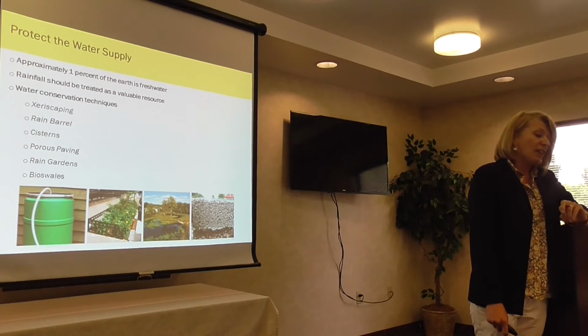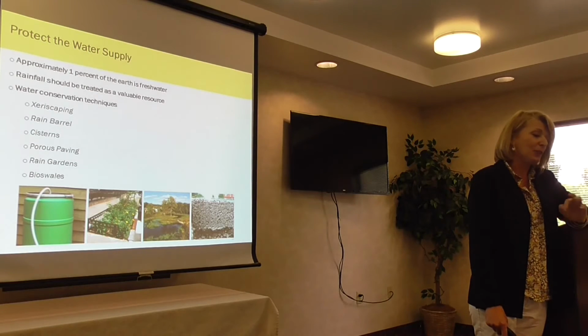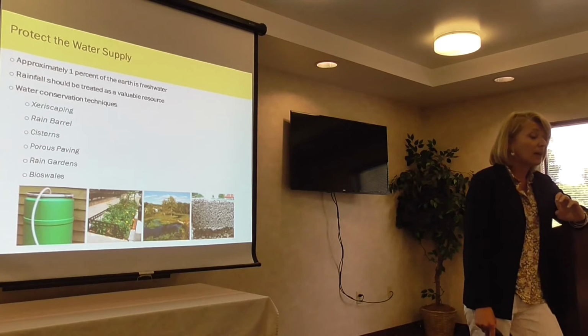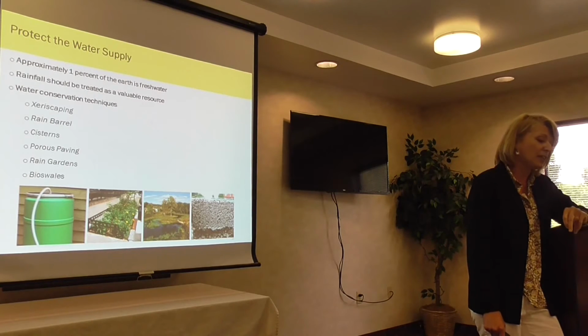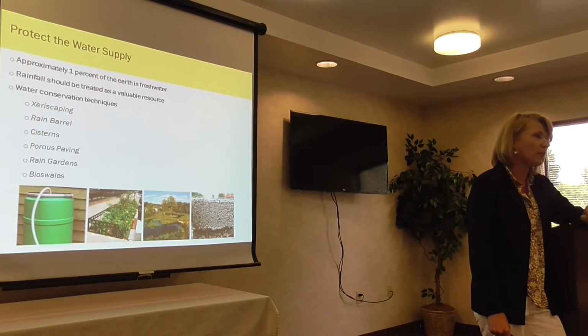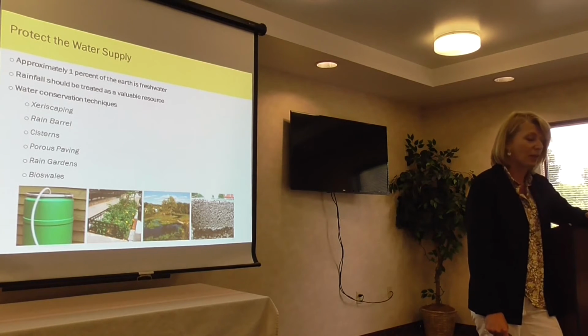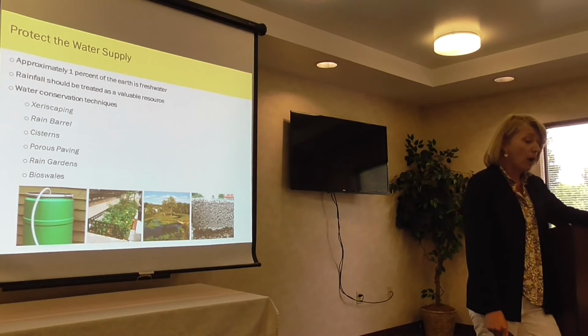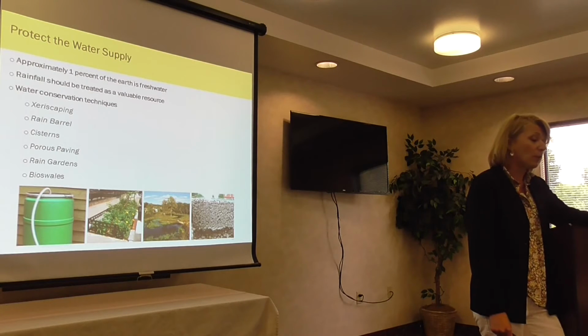So, protecting our water supply. You've probably heard this, about 1% of the earth is fresh water. Rainwater should be treated as a valuable resource, and there are numerous water conservation techniques out there. Everything from xeriscaping, which I think is a big term in the Southwest, especially with the drought going on, basically planting plant material that doesn't even need water, and using rain barrels, cisterns, porous paving, rain gardens, and bioswales to help protect our water supply.